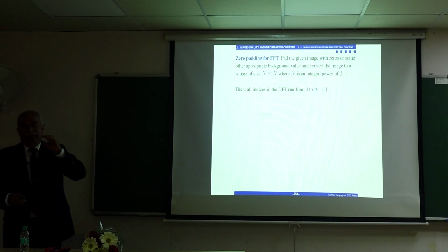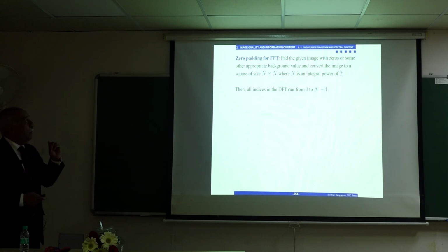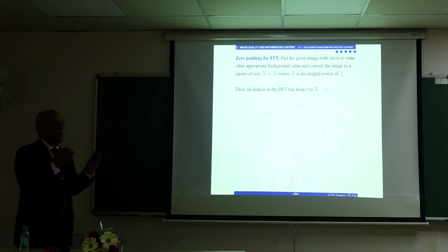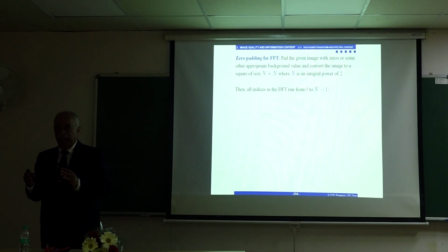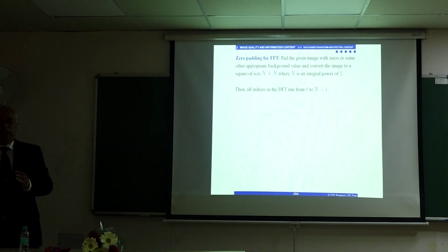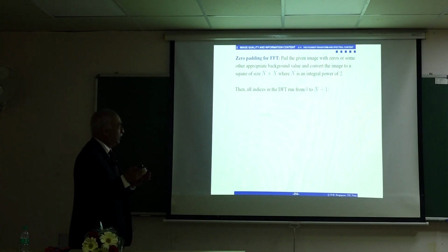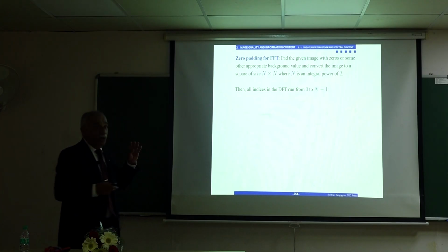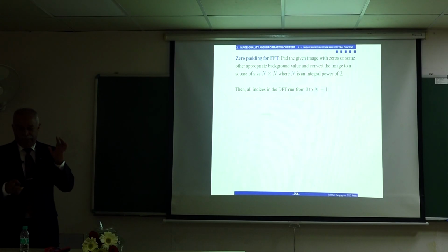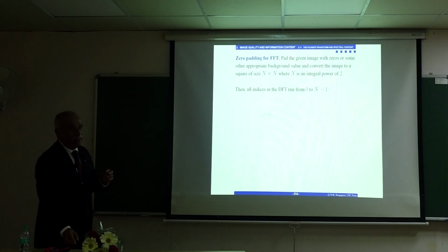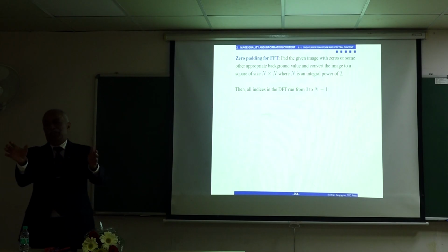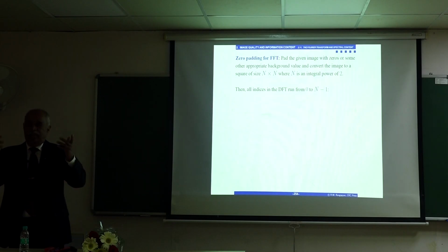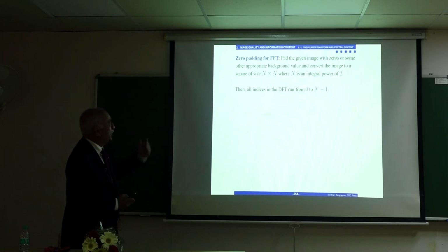And then, with the FFT, having an array of the input data with the number of samples being 2 to the power of n, 64, 128, 256, 512, 1024, and so on, was an advantage for the FFT algorithm. So if you have a signal that has 72 samples, you would add zeros at the end, make it 128 for faster computation. So that's called zero padding.